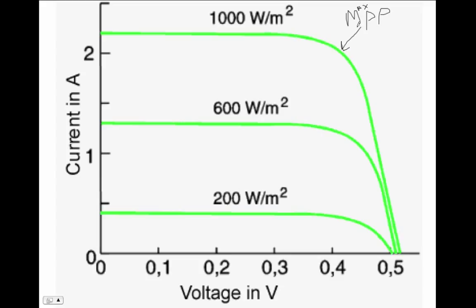And that's called a maximum power point tracker, or MPPT. That's a special kind of charge controller that can get you maybe 10, 15, 20% more energy over the course of a year, with a special charge controller that tracks this point and keeps it. It's not the same as tracking the sun. This is something that's done sort of invisibly. This is an electronic tracking of making sure that the solar panel can always operate right here regardless of what the load is.